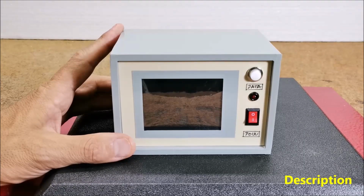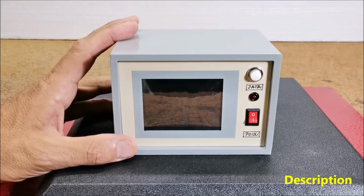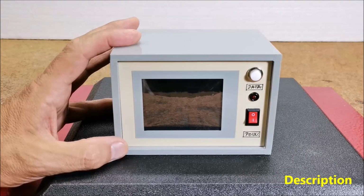One thing to note is that the sensor has a certain lifespan, and the datasheet claims up to 8,000 hours. If you run the sensor continuously, that's not quite a year, so you might want to think about how often you will power off the device.